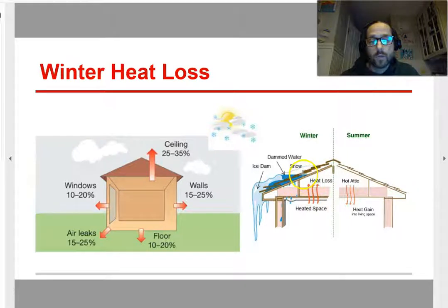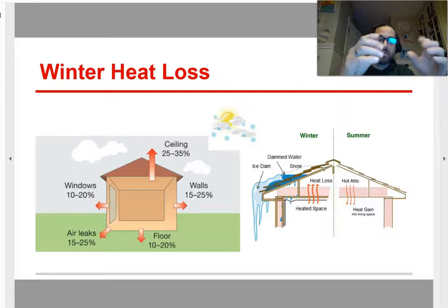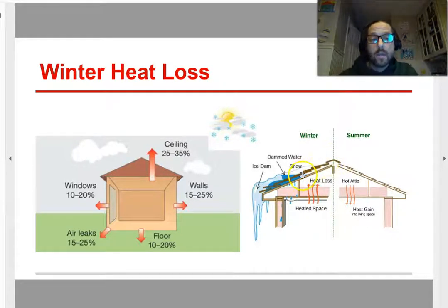So here's one really good example of this. If you ever go around a neighborhood in the winter time and there's snow on the roofs and you see some bare spots, pretty prominent, not just a tiny bare spot, but a real bare spot on the roof where the snow has melted, that's very often a sign that there's heat escaping through the insulation in the attic, and then that gets up to the roof, and it heats the roof and melts the snow.